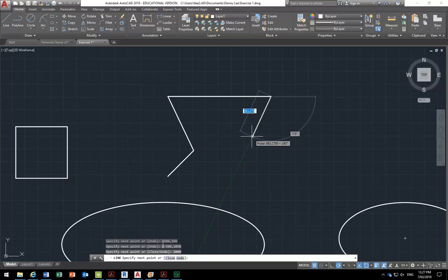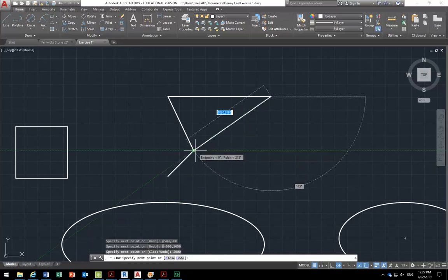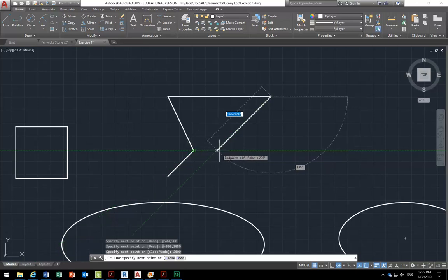So now, if you remember before that method I showed you to track, we can pick up the corner point there, the end point of that point that we've already established, moving to the right. So notice how it's projecting from that point, because I don't know how long this line is. I have to do some trigonometry to work that out, but I don't have to. I can just find that angle, 245, and project from the other corner.